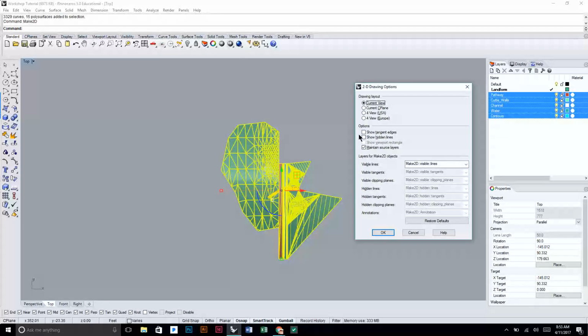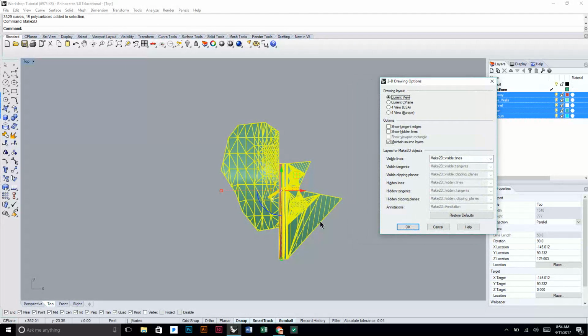And it actually organizes it really well so that it'll create a layer of all the solid curves, and then a separate layer for all your hidden curves. So when you go into Illustrator, you can select your hidden line curve and make those dashed lines versus everything else being a solid. So it becomes really powerful in how you can start to assign curves by their properties.